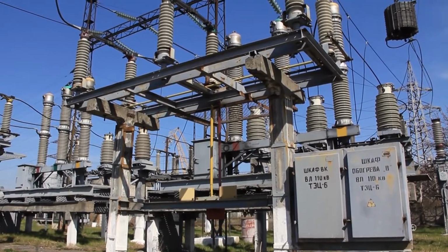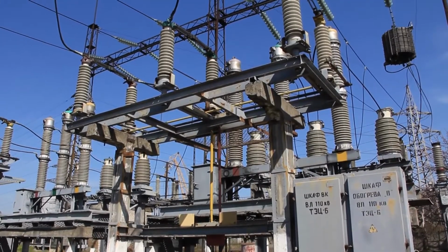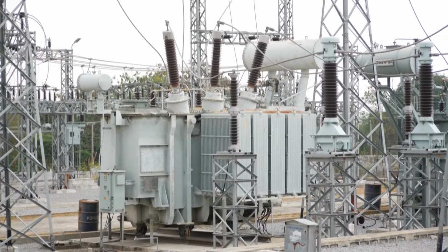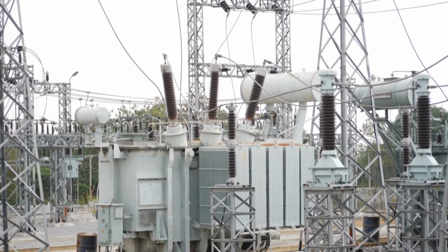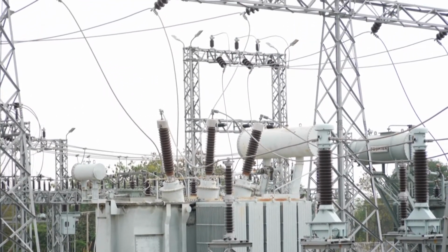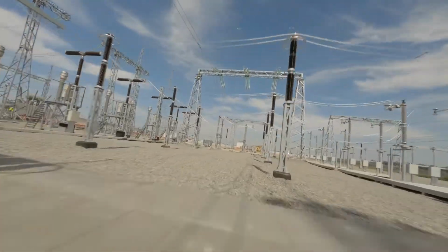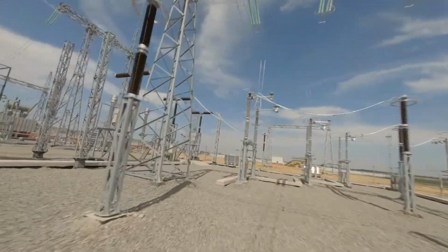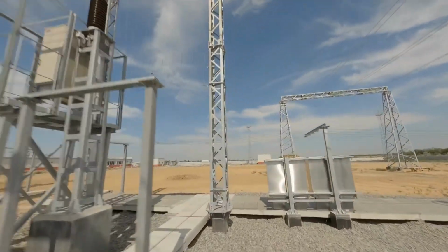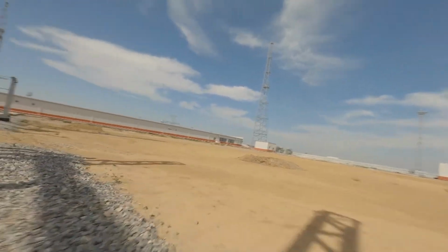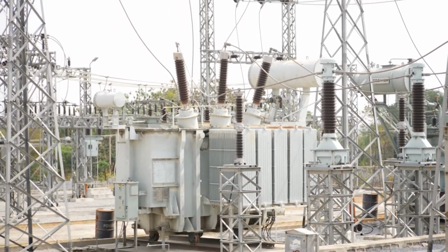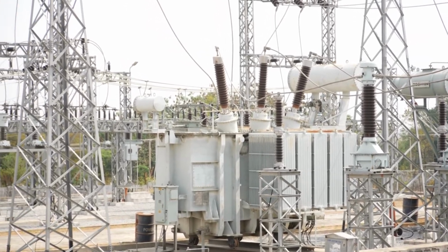A transmission substation is a facility where transmission lines terminate or connect to other transmission lines. Transmission substations contain equipment to sectionalize the power system and disconnect faulty equipment or equipment requiring maintenance from the rest of the power system. It is usually desirable to reduce the transmission system voltage before the electricity reaches customers. Therefore, most transmission substations contain power transformers to step down the high transmission system voltages to lower sub-transmission voltages.